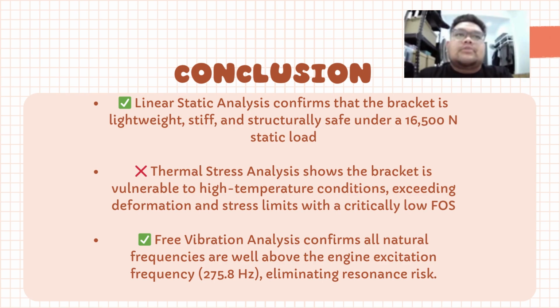For the conclusion, the linear static analysis confirmed that the bracket is lightweight, stiff and structurally safe under 16,500 Newton static load. But the thermal stress analysis shows the bracket is vulnerable to high temperature conditions, exceeding the deformation and stress limit with a critically low factor of safety. The free vibration analysis confirms all natural frequencies are above the engine's excitation frequency of 275.8 Hz, eliminating the resonance.